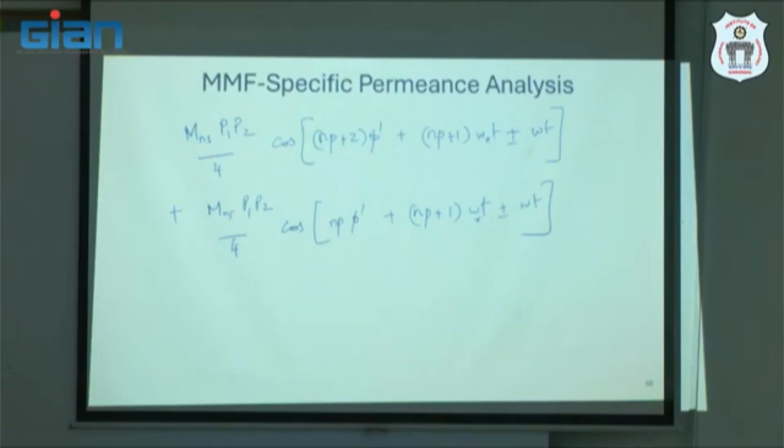So these are all flux components from the rotor frame of reference, right? Because we are looking at angle phi dash. The same flux, if we look at it from the stator frame of reference, this expression can be rewritten in this form.